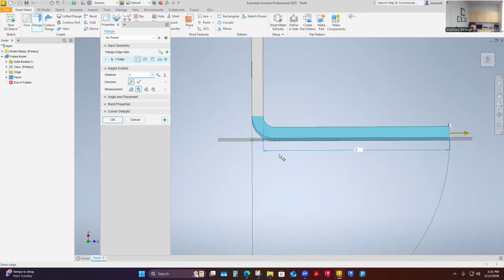When I think of sheet metal, I do think of origami, folding a 2D shape, a flat profile, into a 3D profile in some ways, which we do with origami as well, right? And so those bends and those overall lengths, these stretch outs, these flat patterns, are affected by my selection, how I want these to bend, and what dimension I'm really truly looking for to finish with. And this potentially affects just the overall flange length. And so what do I got here? I've got maybe from selected edge. So now it's going to be 2 inches from that inside edge.